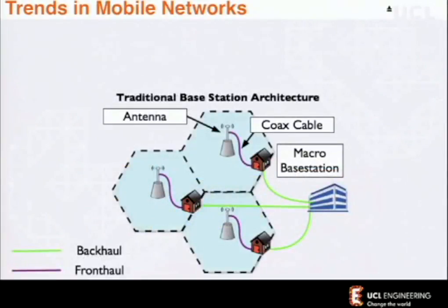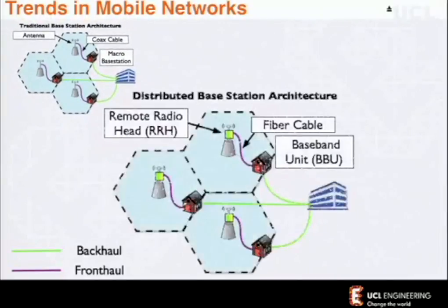Until the last 3 or 4 years, where the concept of front haul has started coming through, but done in a rather different way. So the idea here is this is what this would typically look like. Maybe fibre connections, microwave connections out to these little base station huts, and then the coaxial feed up to the tower. We've started to see that these are being replaced with remote radio heads. So the very last part of the electronics is now moved much closer to the antenna.